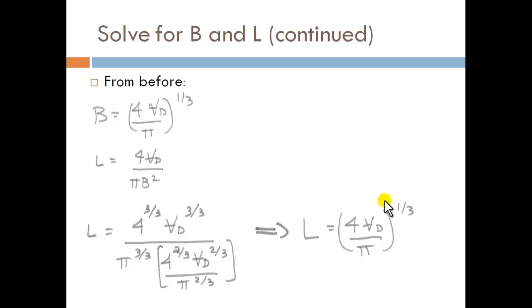look at the heat transfer losses from an internal combustion engine, the type that we studied during the first module of this course. If you minimize the surface area to volume ratio there, then you also tend toward minimizing the heat transfer to the wall, and thereby you increase your efficiency. Now, that's almost like a first-order solution to that problem, if you want to think of it that way.